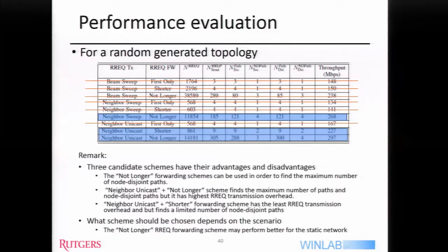Actually, in a mobile ad hoc network, if we keep moving and the link between you and me is disconnected, it may never come back, right? Because we move in different directions and far away from each other, and we don't know when we will meet again. But in 6 gigahertz, the link outage becomes very transient. Like a pedestrian: people move across the link and block it, and after a few seconds they move away, and then the link between you and me is back. So it's intermittent.